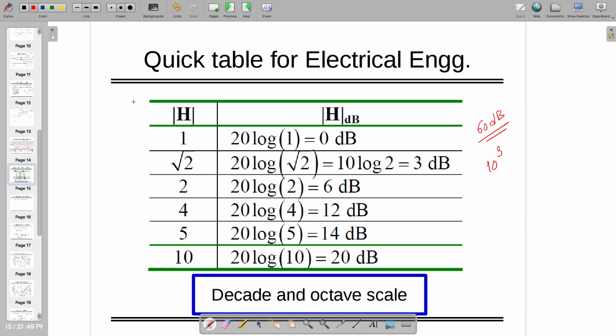So you can look at this table and you have to remember a few things, like 20 log 1 is 0, which is known to you. 20 log 10 is 20 dB, 20 log 100 is 40 dB, 20 log 1000 is 60 dB, 20 log 10000 is 80 dB, right? So these numbers have to be on your fingertip. When we are going to talk about it, you should convert it in volt per volt if you like, but we are going to talk only in dB. Some people call this dBV also, but dBV is equal to dB if you are taking with 20.